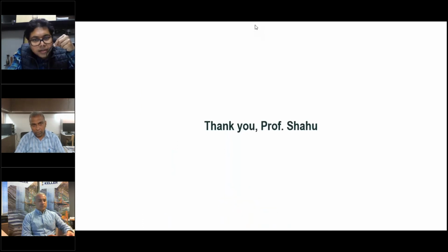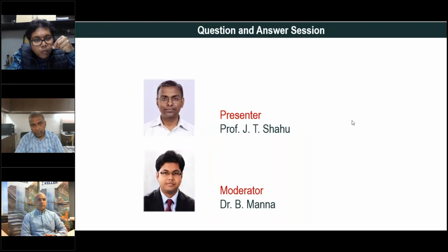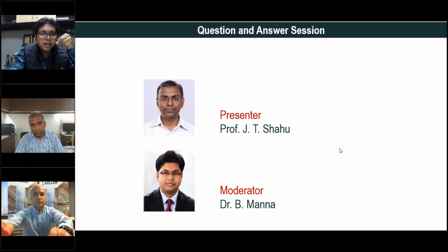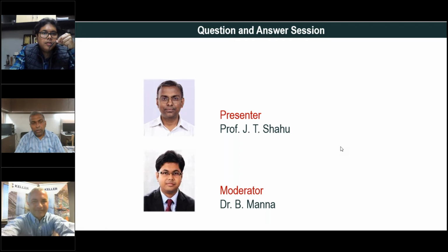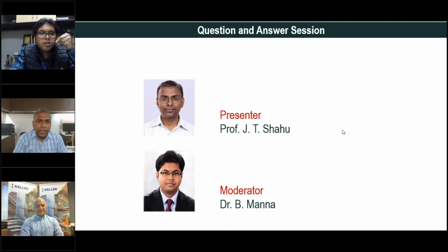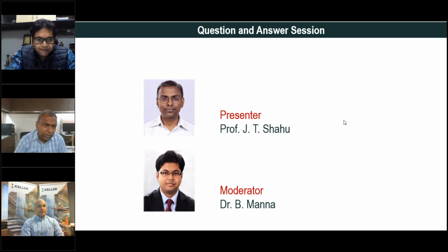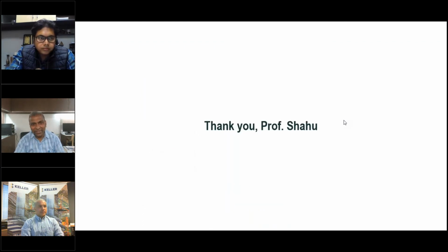Okay. I think this is the last question, by Mr. Bhavin Mara. He is asking what bentonite quality is preferable in piling? So about bentonite quality, there are clear Indian standard instructions in IS 2912, I think that is the code. So you can go through that, complete 2 pages of recommendations are there about the bentonite quality.